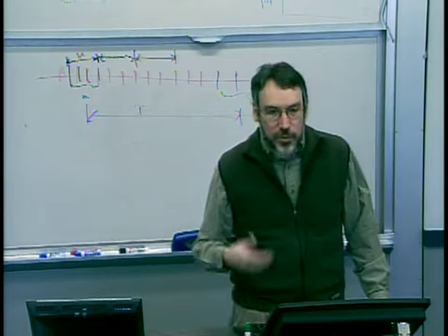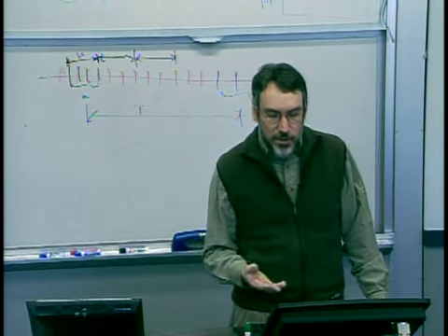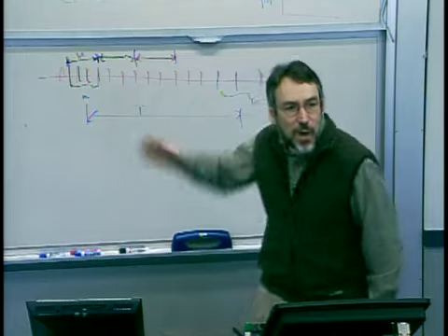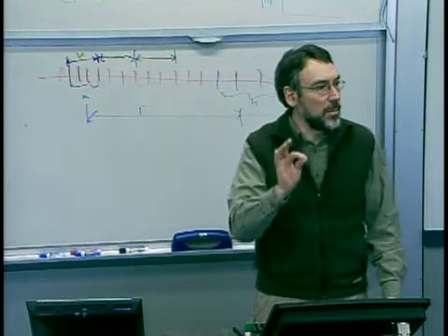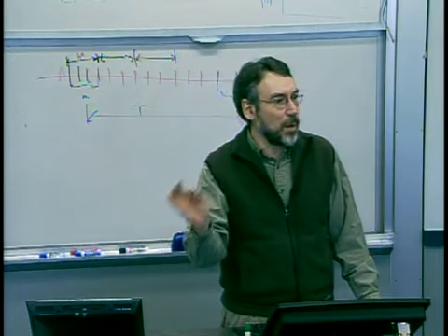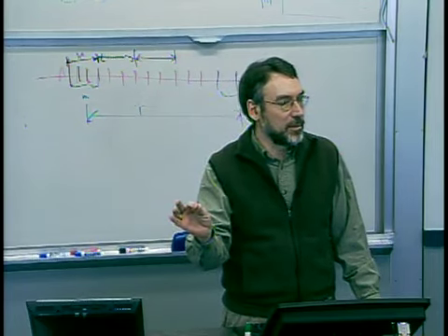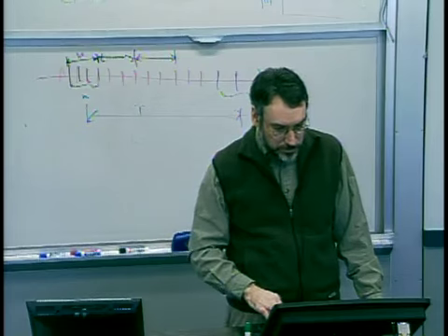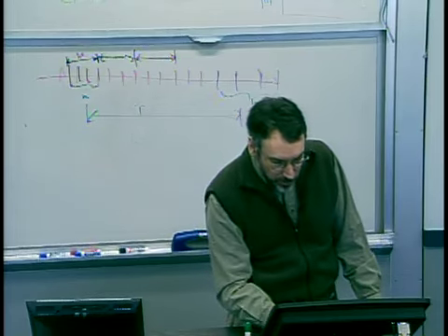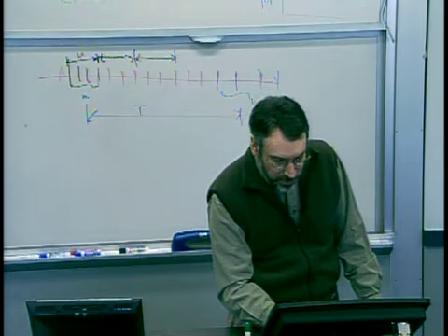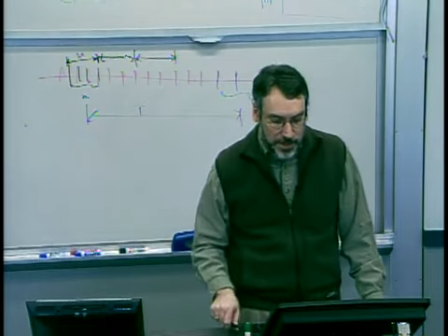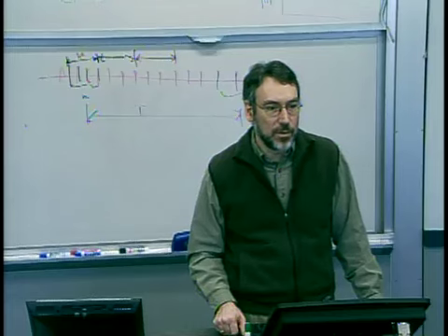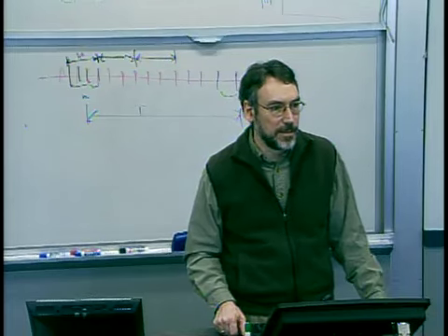So now you can start to evaluate various questions like, what's the probability, not of a false alarm, but the probability of a non-conforming part? And that's easy. You're just looking at the tails. I can go in and say the probability of a non-conforming part up on this side is just that tail to the right, based on the actual performance I need.